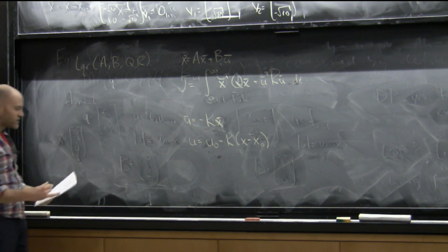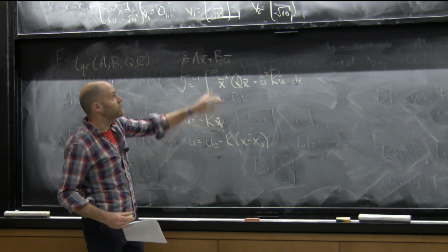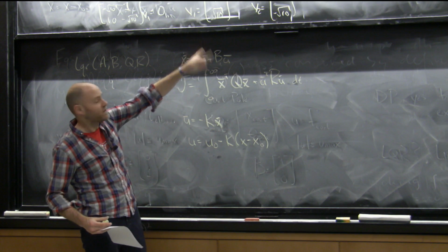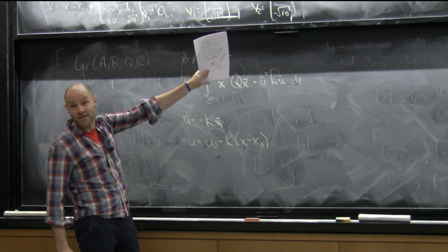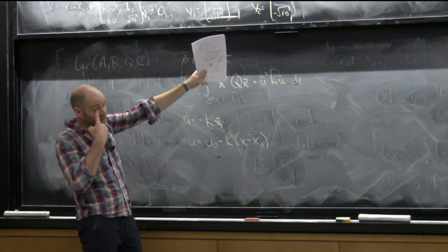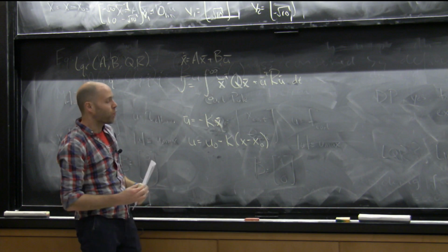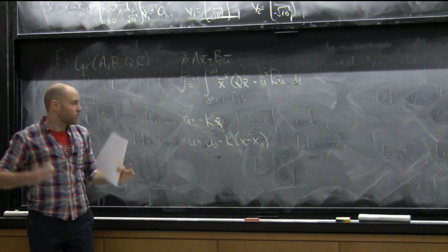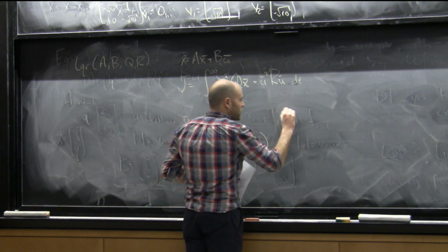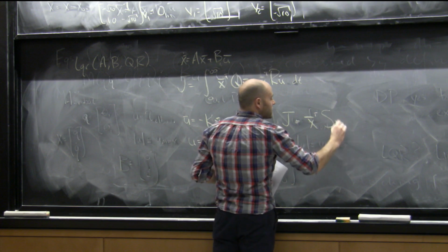So for simple values of Q and R, you can plug that in, see what K comes out to, and see how it changes that, and it's beautiful. You should do it. But I won't do it now because you've already sort of seen it. When we did the value iteration with the quadratic costs, what did we see come out? We saw a quadratic bowl come out. We also know that the solution here, the cost to go, is J(x̄) = x̄ᵀ S x̄.